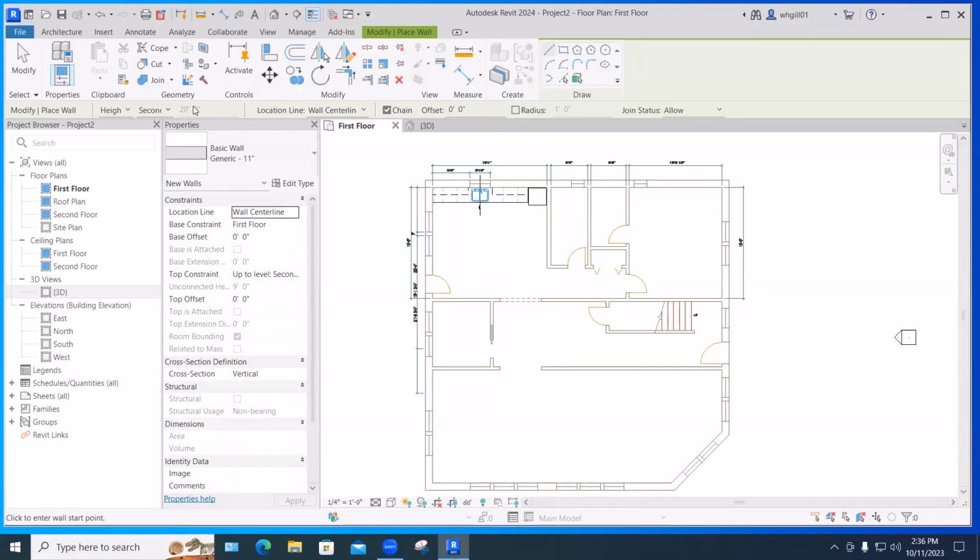And in terms of placing these walls, what I really know, probably what I measured, I mean, this is a made-up apartment, but let's just assume that we measured it, what we actually measured were these inside dimensions. So as I'm indicating my 2 points for each wall, I want that to be on the finished face interior. We don't know anything about the inside of the wall, what it's made out of. We just know where we hit the paint.